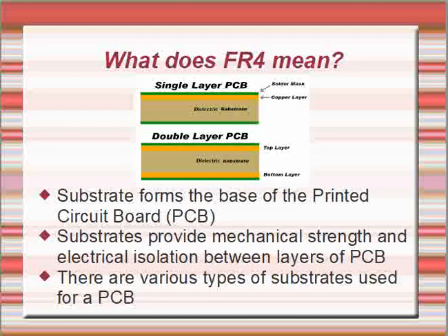Hello all. In a PCB, substrate forms a very important part. Substrate is actually the base of the PCB. The substrates, like if you see here in the image, divide the copper layers in a PCB. They basically provide mechanical strength to the PCB as well as increase the reliability of the PCB, and also provide the electrical isolation between the layers of a PCB.